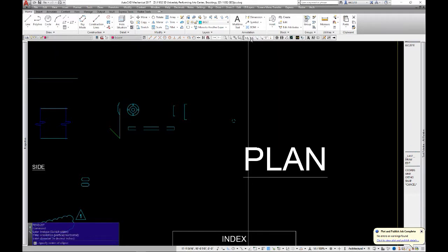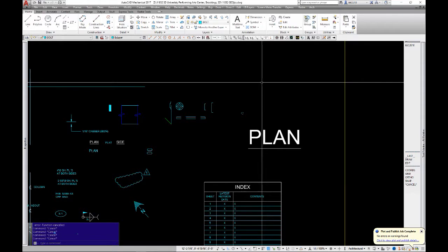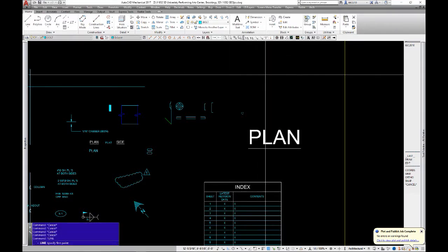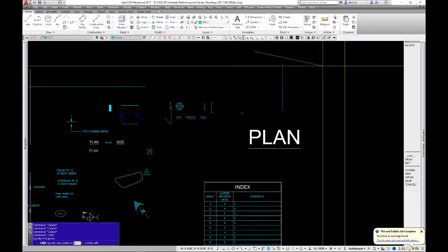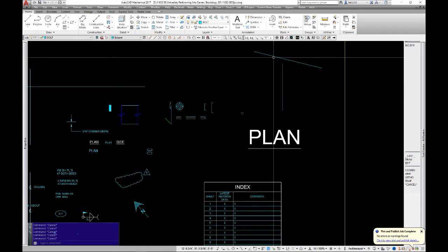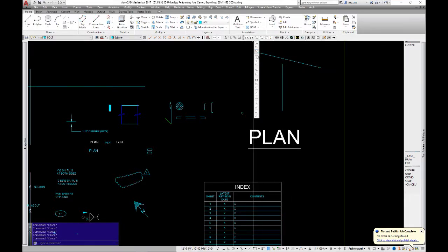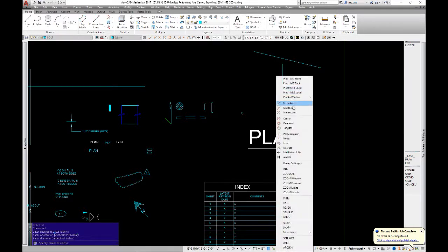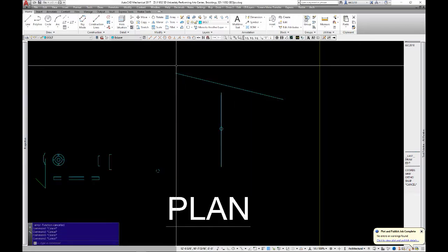This one here is for ellipse. There's going to be times that you have to draw an ellipse in. It's a skewed in plan view, and you need to draw an elevation of it. So you can come here, 13/16, center of ellipse, nearest there, select reference line, and it's going to put that in there for you.